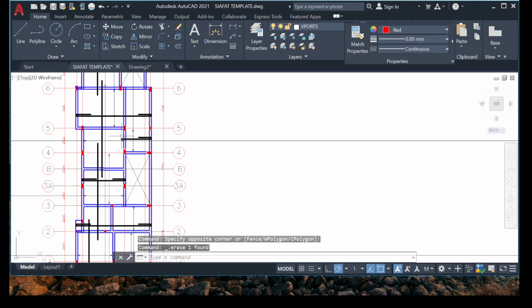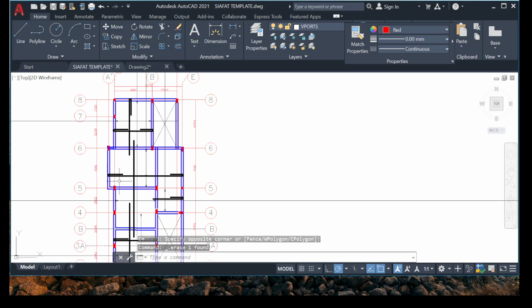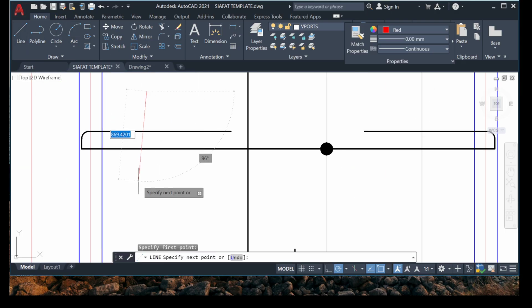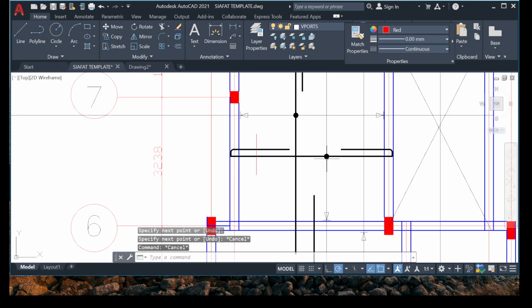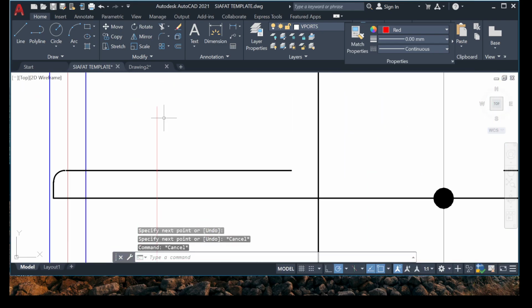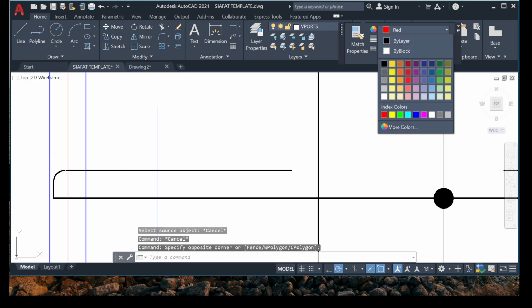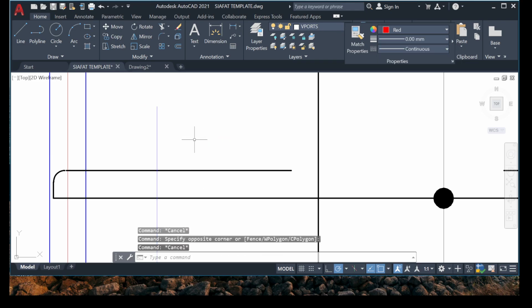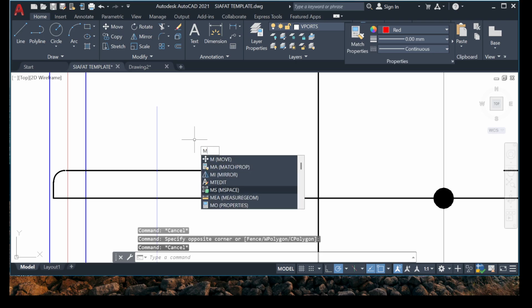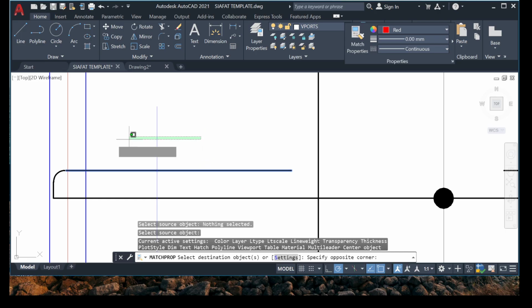Okay. So let's go to the top reinforcement now. Now I need you to pay close attention. For the top reinforcement, I'll use a different color. So this one is a top reinforcement, but this one is a distribution bar. So let's use blue for the distribution bar, and let's use red for the main top reinforcement.